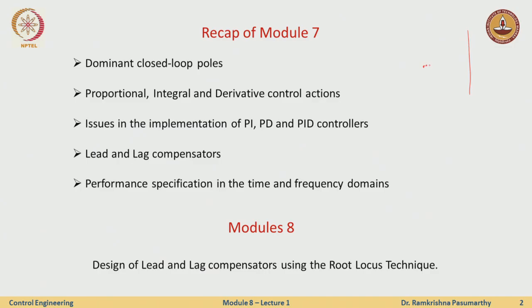So for example, if I take a system which has poles here, here, here, and so on, the pair of poles which decide how my system behaves can more or less be approximated by just looking at these 2 poles, because these transients die out pretty quickly, because we are looking at something like exponential of some number k times t. The bigger the k, the faster they decay. The smaller the k, the slower they decay. So this actually corresponds to smaller k. And if they are on the imaginary axis, then these never decay. It's a constant oscillation process.